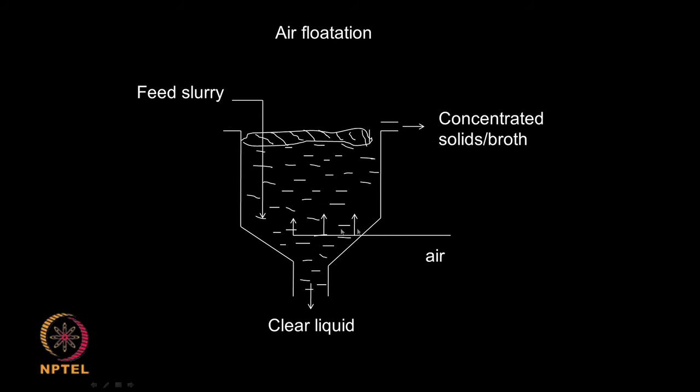So, here you require air. The advantage of this method is that you are not adding extra chemicals and contaminating the setup. You are just bubbling air into it, so that the fine particles are trapped in the air, which can be skimmed out. So, this is much more advantageous than adding a flocculant or a coagulant.